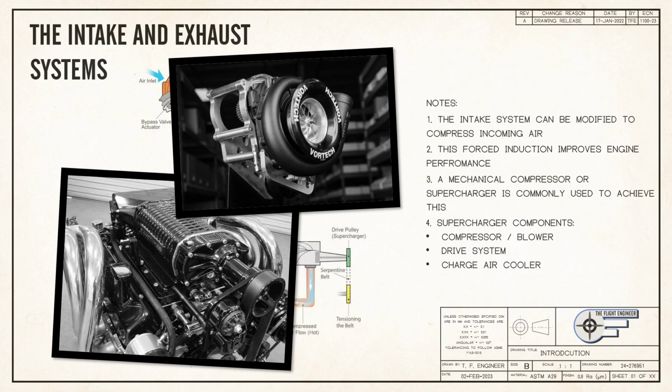Regardless of type, all superchargers will need a drive system that uses either a belt, chain, or a system of gears to drive the compressor off the engine's crankshaft. Because the compression of air inherently generates heat, a charge air cooler will sometimes be used between the supercharger and the intake runners.